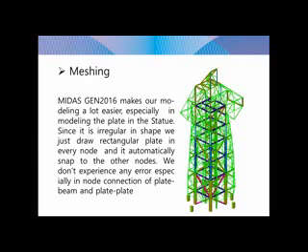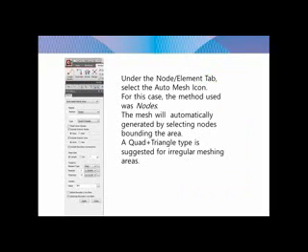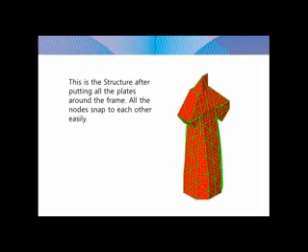We have a video showing how to do it. First, go to nodes, and then auto mesh, then select the nodes, then quad triangular, then assign the property used. Then go first node, second node, then third node, then press apply.